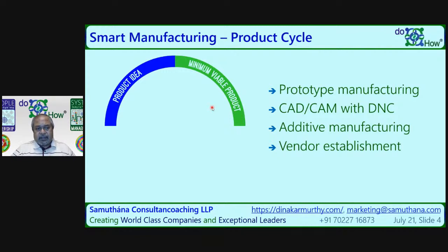Again, engineering is required because depending on the load and depending on the fatigue load, either the part can be 3D printed or has to be manufactured using a cold forged or a drawn raw material. Drawn means hot drawn or cold drawn raw material. Typically, how is the metal manufactured? You've got the particular steel which is manufactured, goes into the furnace, and from there you pour it into ingots. Ingots are massive blocks, and from the ingot it is either cold rolled or hot rolled into wires or sheets or whatever be the way that we buy the material in the market. It could be bars, it could be sheets, it could be anything.